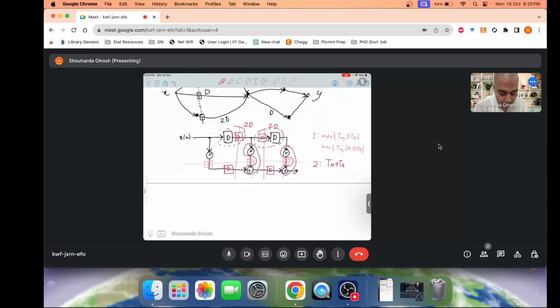But this does not happen for free. These delay elements themselves incur some power. They eat up area, obviously, because they are made of NAND gates in feedback. If you have studied digital electronics, they increase power consumption to a good extent because they are being toggled by a clock. And we are considering ideal registers over here.